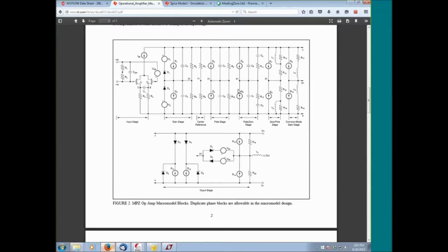So we want to keep in mind the realm of applicability of the models that we're working with. What are the limitations? Usually manufacturers will specify what the models are good for. For example, for power supplies, you can have steady-state models, which allow you to simulate the behavior after all the transients have died down and the power supply is working with a steady load. And we also have transient models that model the behavior when the power supply is just starting up, with all of these power-up issues such as the capacitors charging on the input, which are neglected in the steady-state models.